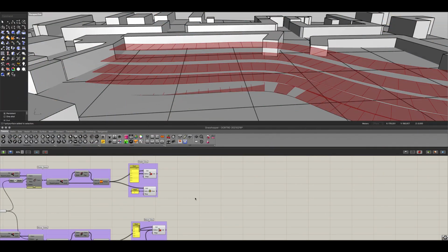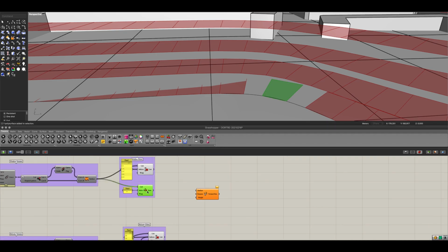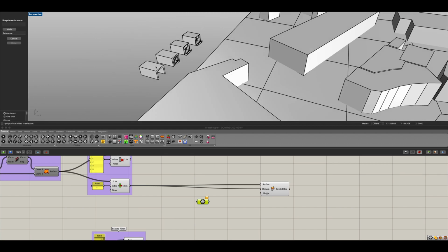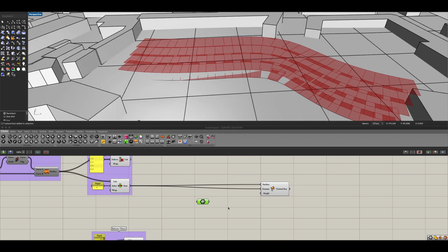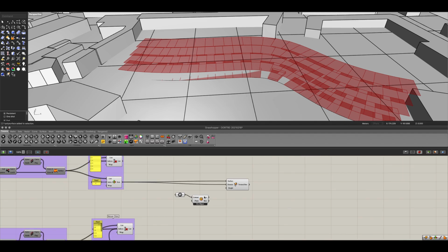Okay, now for the final part, we will finally bring our Rhino elements onto our surfaces. I'm going to start off with the entrance on this surface here, and to do that, we're going to get ourselves a surface box, and we're going to add in our item into our surface input and into our domain input. Let's bring it over here. I'm going to add in a brep so that we can assign our entrance or passage surface. In this case, brep. This one like that. Okay. And now I'm going to use a bounding box. I'm going to connect it into there. And I'm going to also bring in a box morph.